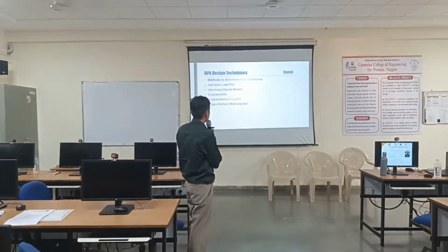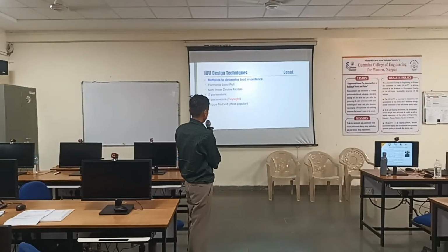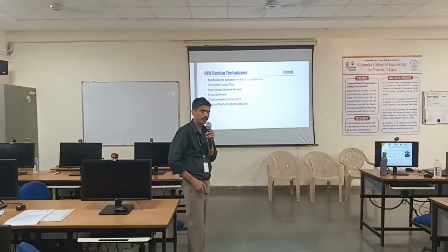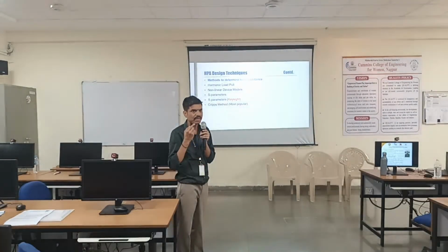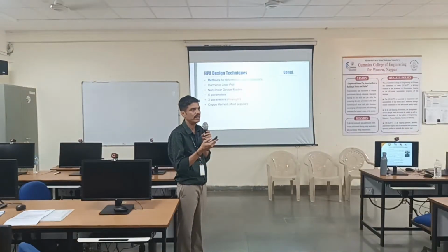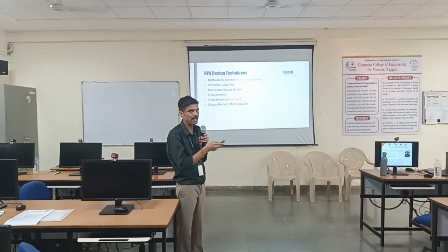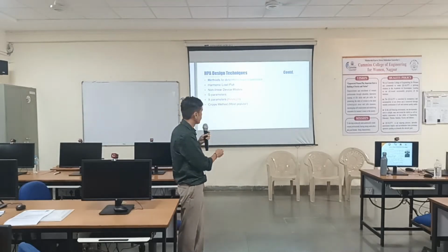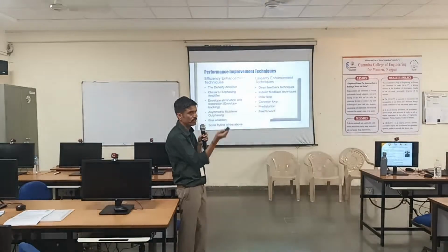There are a whole lot of different options available. The best one is to go ahead with the non-linear device model, which will be provided by any manufacturer such as Macom or Qorvo. You take the non-linear model. I will show you how to get the non-linear model, and that you have to use in your transistor.